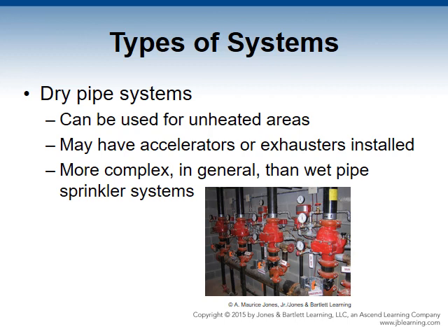The dry pipe valve is the key component preventing water from entering the dry pipe system. They may be dry pipe valves operated on an air to water flow differential or ratio with design principles. For example, the air to water differential may be 1 to 5, where 1 pound of air pressure will hold back 5 pounds of water pressure. When one or more sprinkler head activates to reduce the air pressure, the air to water ratio is disrupted, thus allowing the water to come and fill the dry pipe valve, causing the clapper valve to swing open and begin to flood the system.